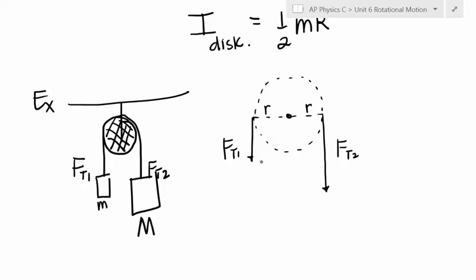If you wanted to reduce the effects of the pulley, what could you make this disc out of? Or how could you redo this design? Make it a hoop. You would reduce the moment of inertia. Or take out the middle by reducing the mass, yes. Okay? But if you had to have a particular mass, having a disc would have a lower moment of inertia. Right?